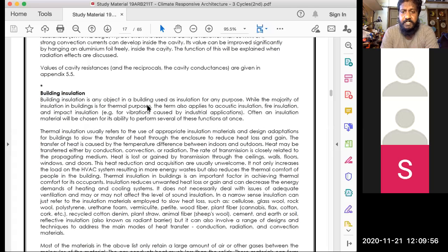But what are the further reasons? This is very apt in a hot place or a much cooler place also. When any indoor space is being kept much cooler, as in a colder place, we don't want that cold to stay throughout a very long period, like a month or two. What happens is it starts to form moisture on the inside, and we start to develop molds. Molds are fungi, which is not a healthy sign. So that is another important reason we need to look into.